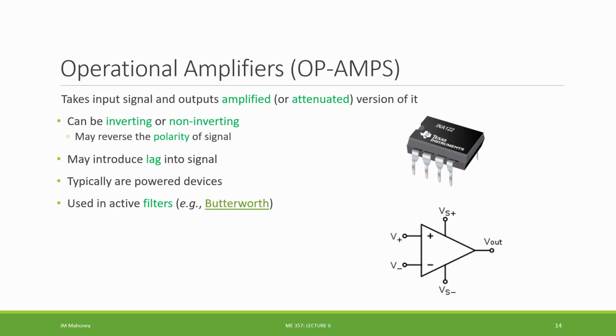Let's say that we are reading a sensor that's maybe a thermocouple or an accelerometer. We're putting it through our circuit that features an op-amp, and part of what we're trying to do is filter that signal. So there might be high frequency noise or low frequency noise in the original sensor's signal. We're passing it through our circuit in order to remove that high or low frequency noise.